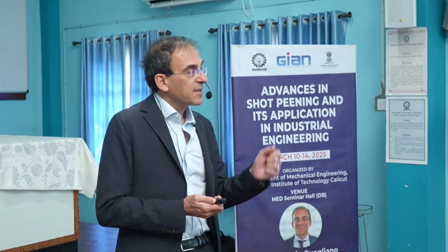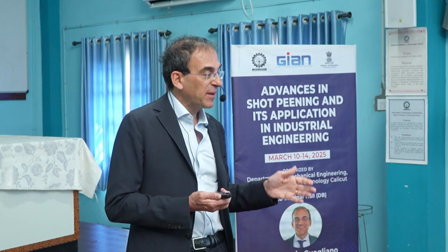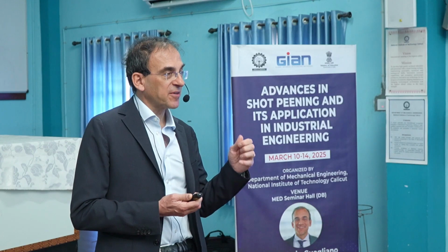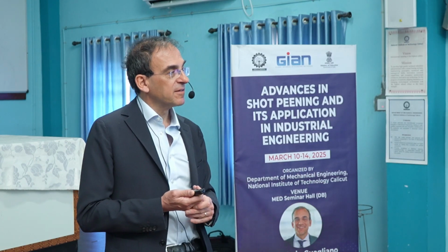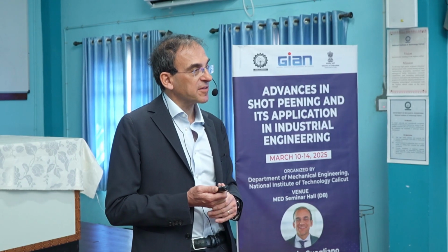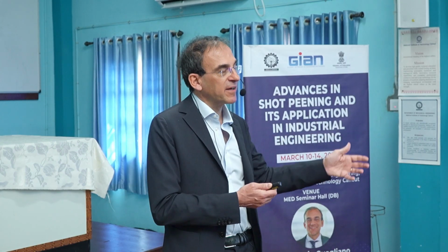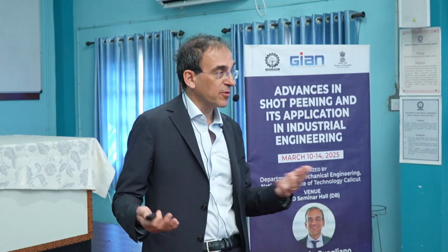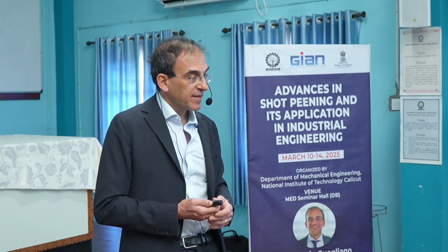It is used for large parts and for mass production. If we need a high production rate, high productivity, this is the right shot peening process. Because it is possible to treat a huge number of parts in the working period, much more than with the other peening processes. So the productivity, the production rate, is very good.